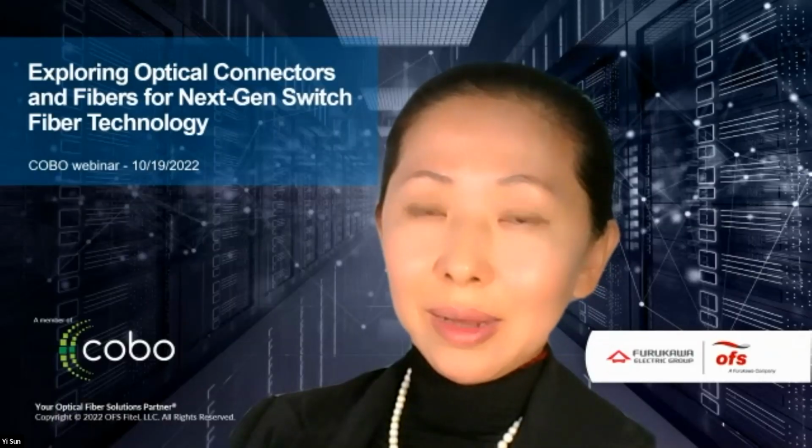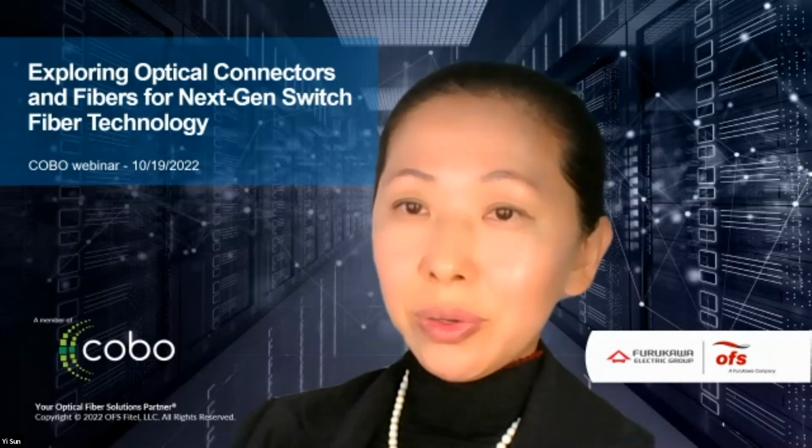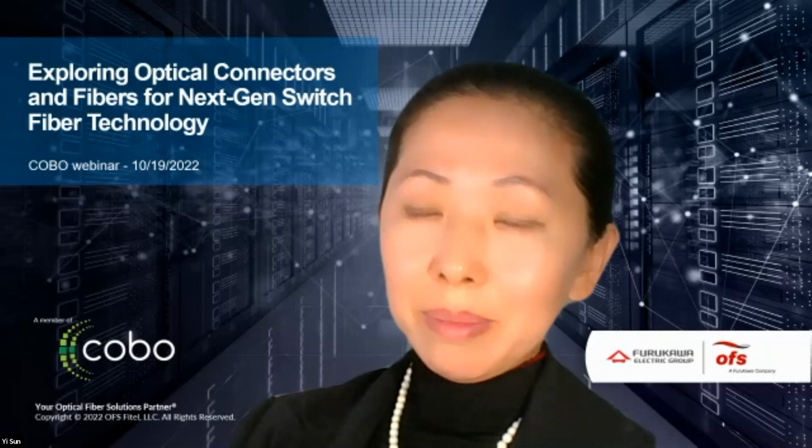Yes, Jim, I'll quickly add, OFS does have an easy bend single mode fiber that would meet those requirements on the single mode side. There's a lot of optimization on the multi-mode side also for bend optimization. It would be a challenge for something like hollow core, getting those tight bends over a very short distance, but single mode and multi-mode are positioned for that. And there are newly developed designs to reduce the cladding diameter, with increased proof test and a high temperature coating, to improve reliability.